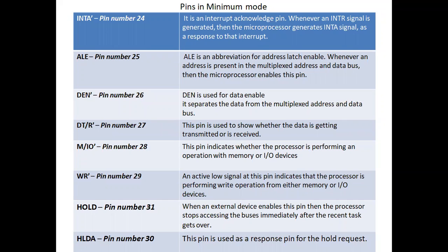When you are transferring data from a CD drive, whenever we are writing some content from the CD to the memory or from the memory to the CD, at that time there is no work for the processor, but our address and data lines are used in this operation. At that time the hold pin is used, so the processor knows not to continue with regular operation, but to hold or wait for some time.